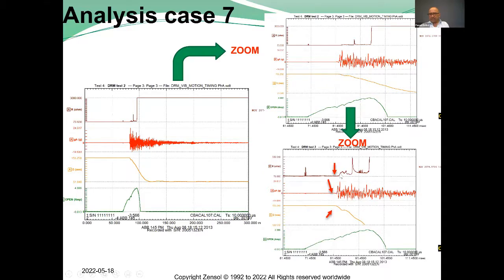You have done when you do all the tests all together. So it's a typical correlation just to learn your vibration signal and how each part of the signal gives you good information on what is going on inside the breaker. So just with the sound, it's like a stethoscope exactly. I cannot say better than this.